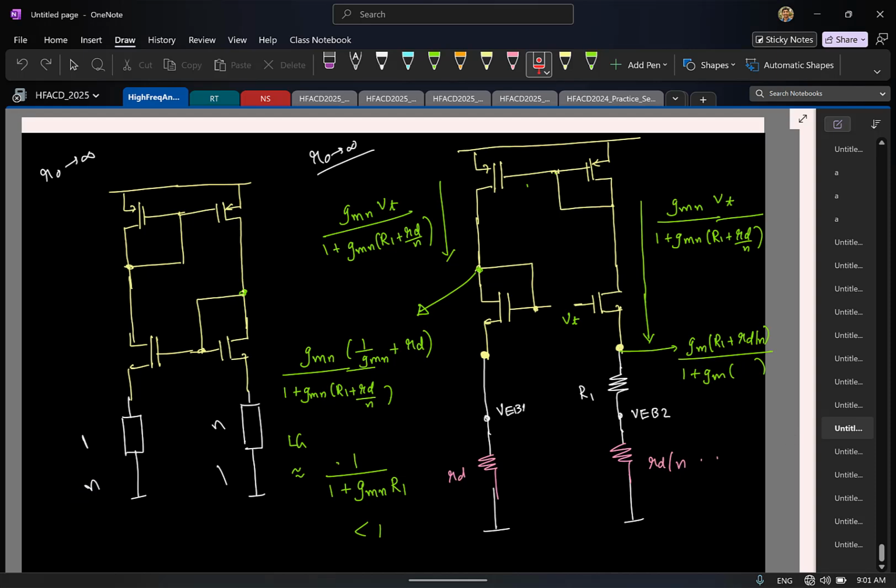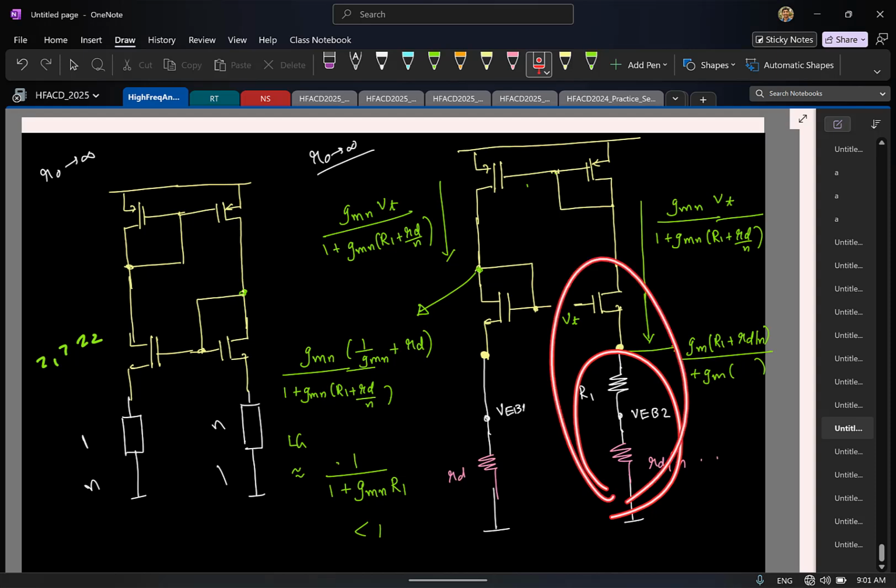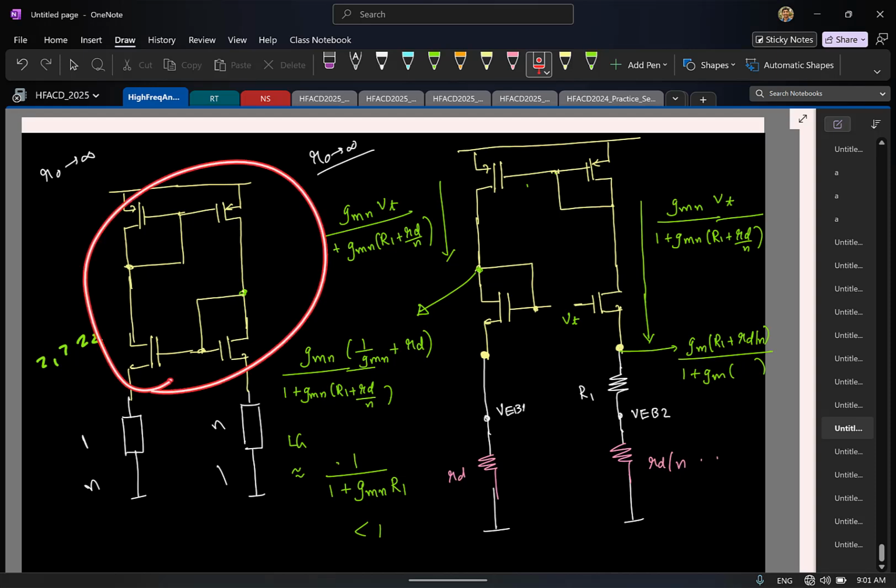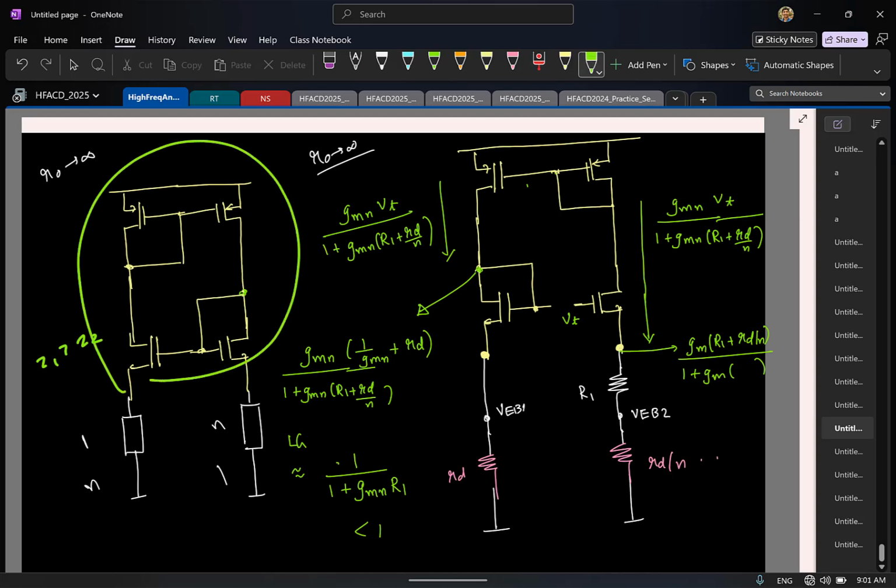So generally if you have two impedances, let us say Z1, Z2, and if Z1 is greater than Z2, you put the larger impedance on the source side so that provides a stronger source regeneration. Okay, that's the whole idea. And this structure is sometimes referred to as the floating mirror. Again, this essentially keeps the current in the two branches equal, at the same time ensures that the node voltages here are also equal. This is some jargon you might find sometimes.